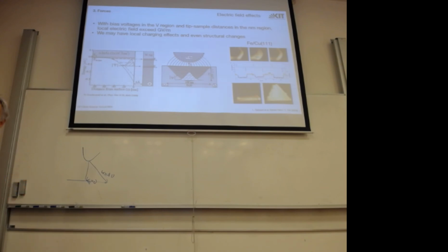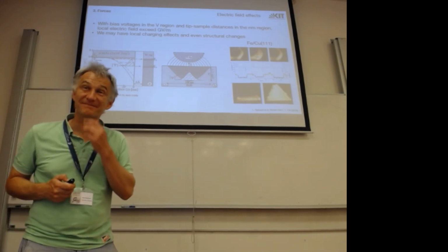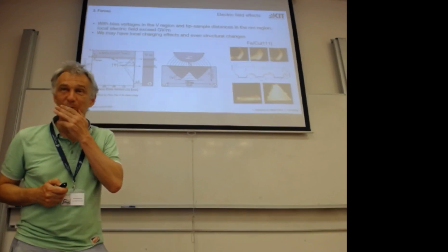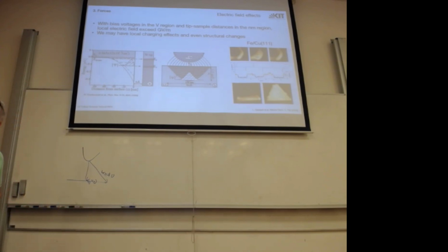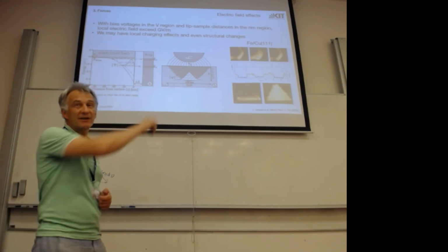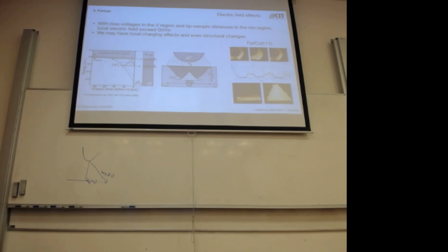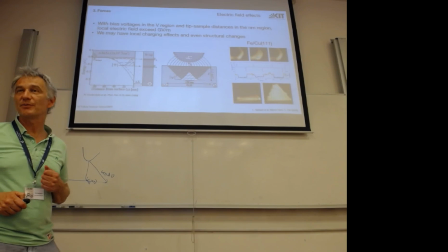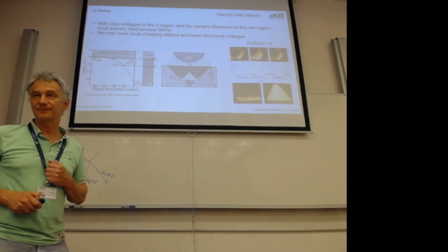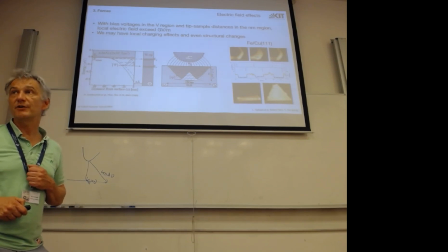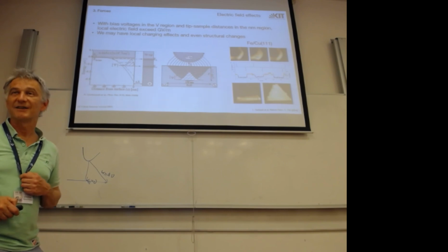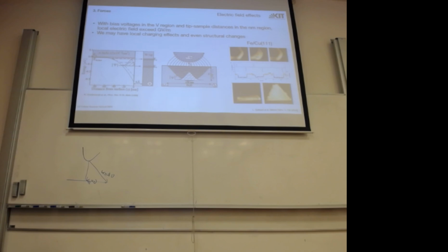Is it possible to use a semiconductor tip? Yes, people are also using semiconductor tips. There is a very big project going on in Aachen where Markus Morgenstern even uses heterostructures to amplify the tunneling current directly at the tip. That's like a MOSFET, this is the gate, and the charges transferred to the tip will induce a very large current. Then you can get sensitivity to single electron tunneling events, which is quite nice. But semiconductor tips exist.